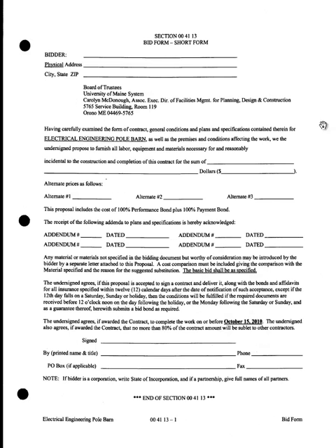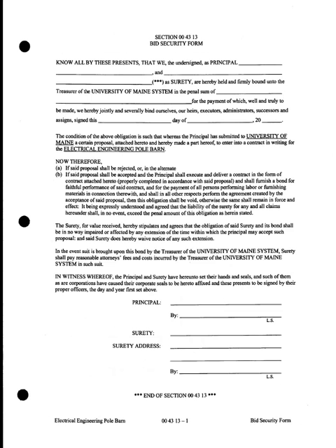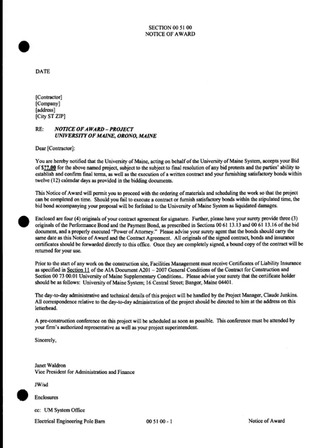Here's the bid form. This is what we actually open up. The name of the bidder, their address, who they sent it to. Here's the description. They're going to give us a price of so many dollars. They'll give us any alternates we may have asked for, and then they'll acknowledge addendum 1, 2, 3, 4, however many addendums we put out. They'll acknowledge they received it, looked at it, and put a date here. They'll sign the bottom, and then it'll be stamped and notarized. Their bid security form is here, which tells who the insurance company is that's going to insure them. It may be just a form from their own insurance company.